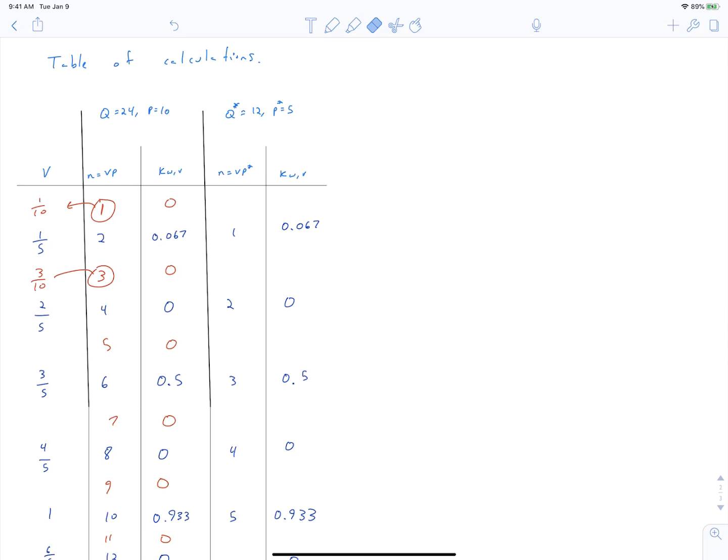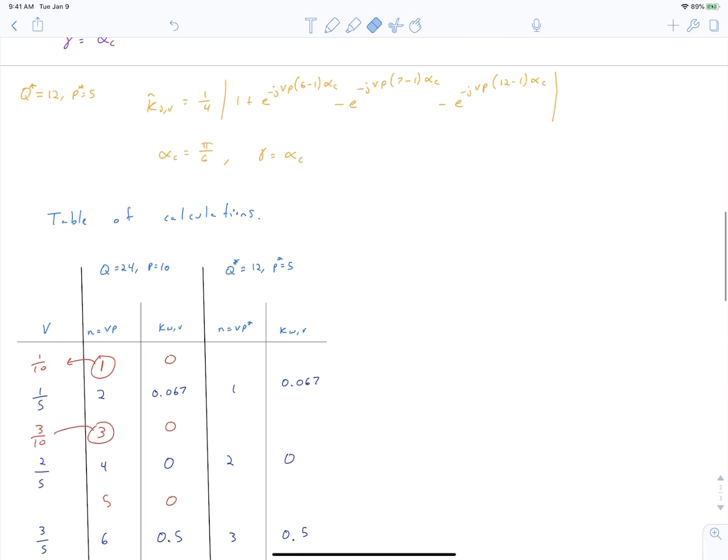And this is useful, again, because the base winding spans multiple combinations of slots and poles. So any time that you have the same value of q, lowercase q, slots per pole per phase, you're going to have the same base winding. That means that you could be considering designing a winding that is 24 slots with 10 poles, or a winding with 12 slots and 5 poles, and you're going to end up having the same base winding and the same winding factors.